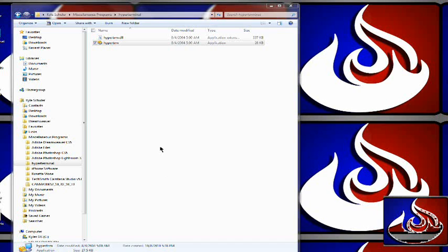Okay, this video is to show you guys how to use Hyperterminal to connect to a Gamewell 600 series fire control panel. Unfortunately, Windows 7 operating system does not come with Hyperterminal, so you can Google it or use any search provider on the internet to find a free version.